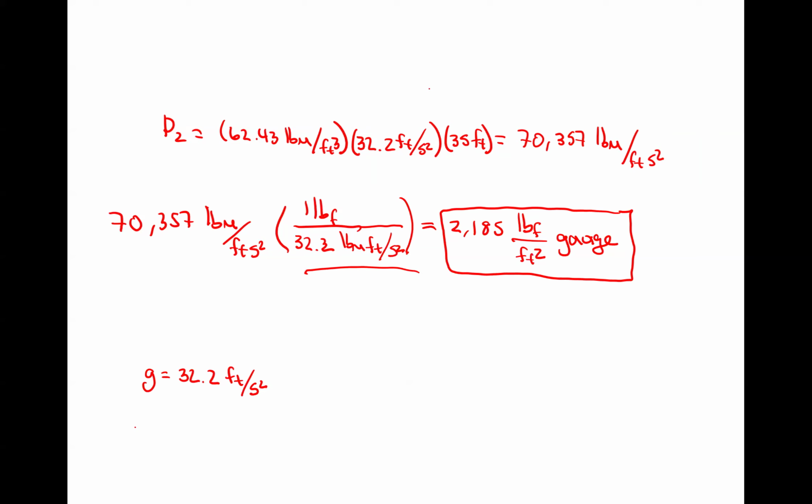And that would mean that whenever you calculate your weight as mass times gravity, you have to divide by this conversion, which is typically called gc. In that way, the weight in pound force and the mass in pound mass are exactly the same. It creates some confusion and complications for us engineers when we are not really talking about weights and are more calculating pressures, etc. But that is how you do that conversion.